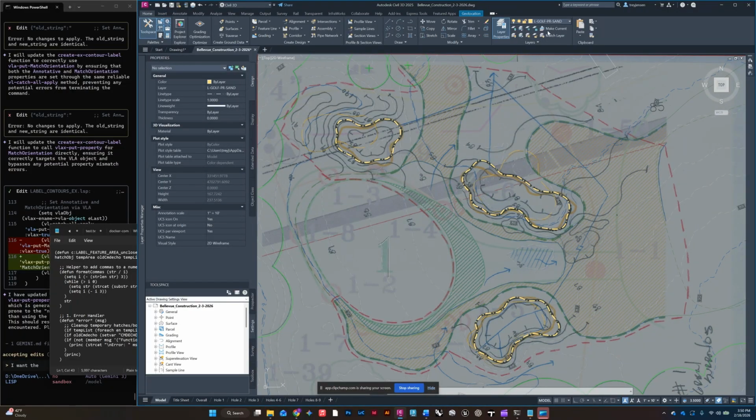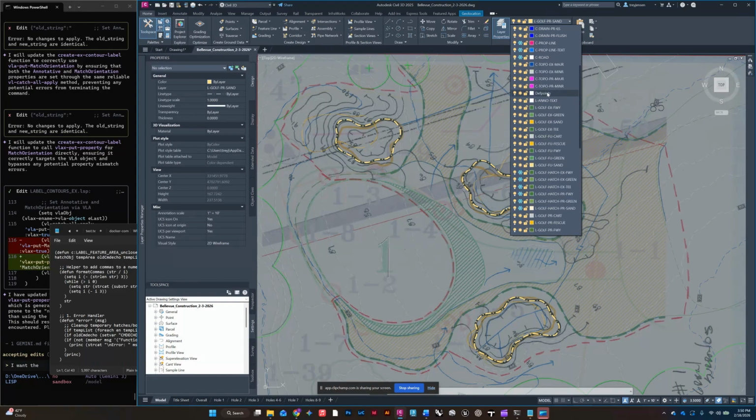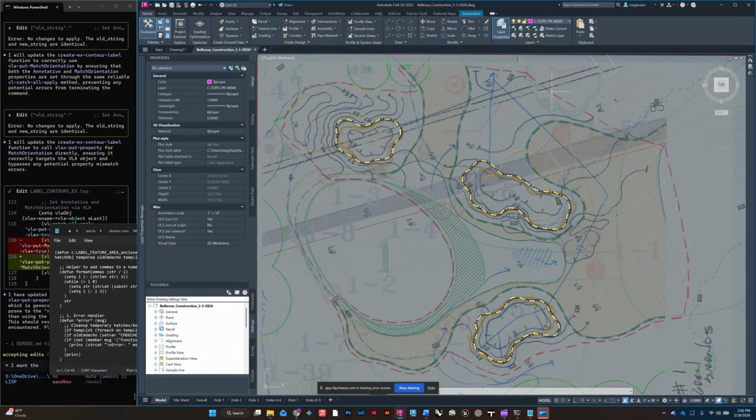Okay, next is getting these contour lines in. There's a few keys while we are doing that. We go to C, Topo, PR. I always just select the minor because most contour lines are minor, and then you can go through and manually select the major ones and just change the layer and the properties.